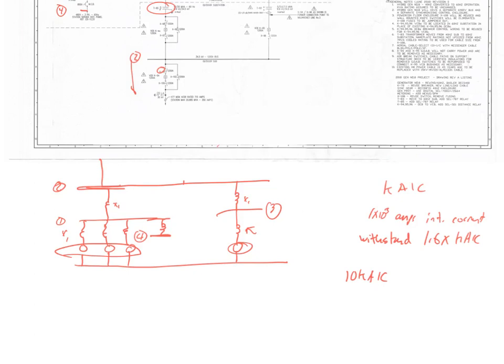Okay? Do we need to actually build Y-bus, or do you feel like you can build Y-bus pretty easily? You can build Y-bus, right? No, I guess for the zero sequence one, we should build one. Well, I'll do it for zero, but for positive and negative sequence, you can probably do that pretty comfortably. So what did I do when I built my positive and negative sequence diagrams? Did I even give a hoot about how the transformers were connected? Did I once tell you to look at how the transformers or the generators were connected? Don't even care. This has zero to do with it. Why is that again? Help me out. Because it's balanced current. Keep talking. Because it's balanced currents. What does that mean?